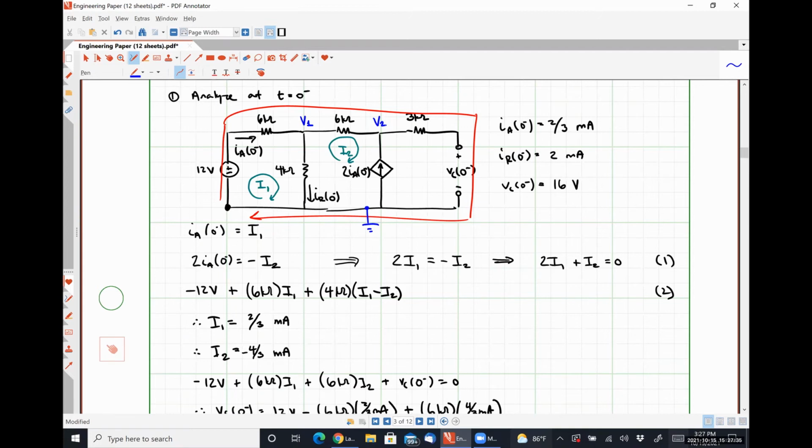So that's why I believe nodal analysis would have been a better method by which to solve this particular circuit, because the currents would be easily defined in terms of the nodal voltages, and that voltage VC is given to us instead of having to work for it. But we can absolutely do it using mesh, because we just showed how. So.